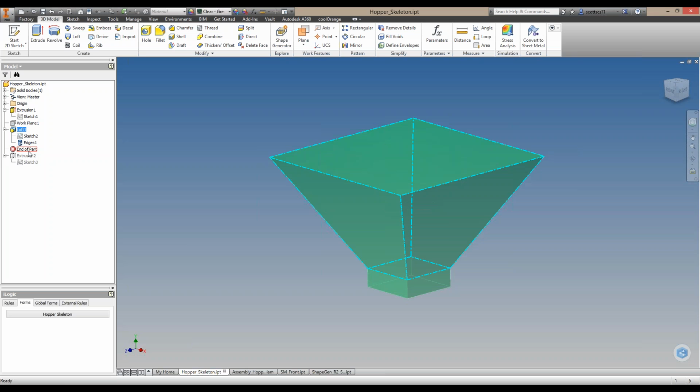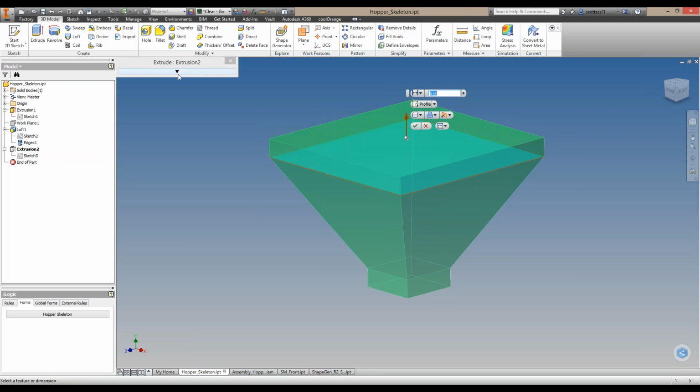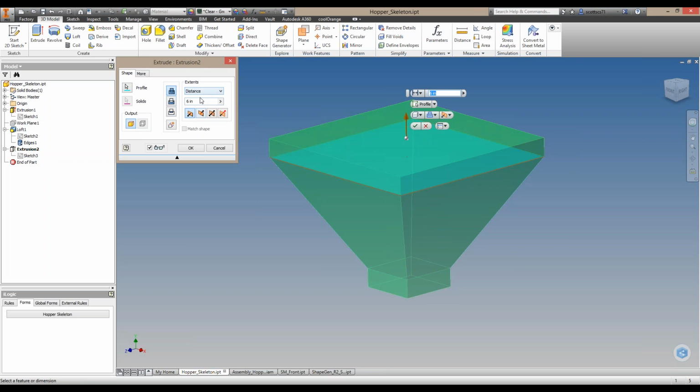So when we go into our iLogic code, it's going to be very, very easy to map those parameters together. And then we'll take this last end apart, drag it down, and you can see I'm basically taking the outside shape of that loft, not dimensioning it, just doing a project geometry and then giving it a height. And of course, if we look at that extrusion, you'll see that that extrusion is also set to a parameter, so section 3 underscore height.